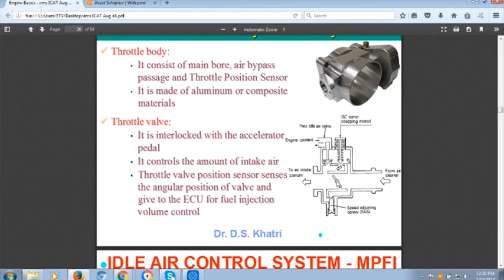And with that, another thing, the practical problem which is coming, if you are going to Leh Ladakh or any cold conditions. This throttle, now this point you listen carefully. When you are not putting your foot on the accelerator pedal, the position is like this. So when the position is like this, it will send around, suppose, 45 milligram of air, just for example. And the data is very close to the real for an 800cc engine. 45 milligram of air is going to the engine.